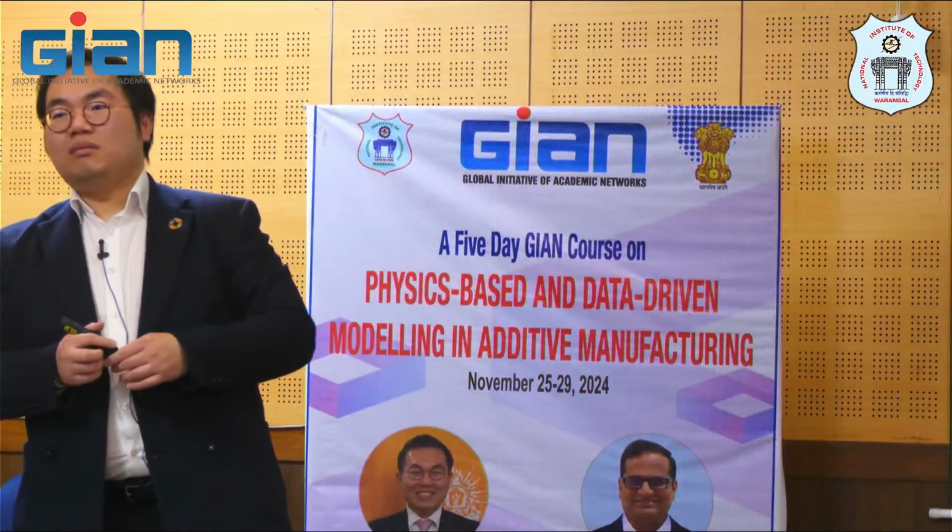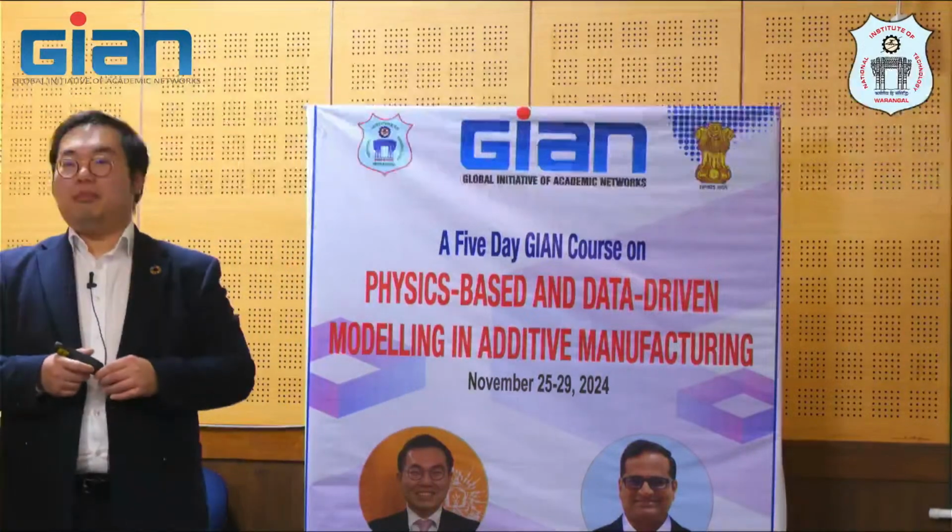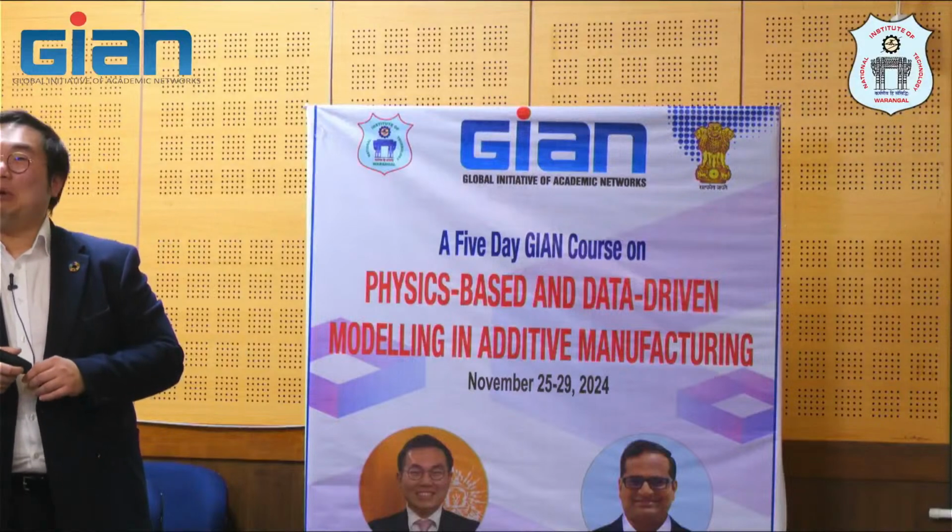But what we see is that the segregation here actually stops the crack. I'm talking about yesterday's talk: it stopped at the solute trapping zone. So that's why we hypothesize this may play some role in stopping or eliminating the crack. And that's why in the new alloy system, this segregation is not concentrated, but uniform, what we call solid solution. It's solid solution in the material. So there is no preferred segregation in the as-printed soft condition. Everything is there in the solid solution. I would say minimum, just for the sake of science. Possibility is low.